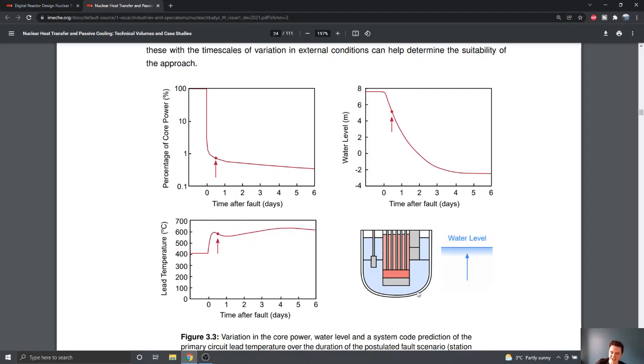You can imagine this is sitting in a really cool bath below where the water is, but above, these regions of the reactor are going to get really hot. And so you might naturally be concerned that these components near the top, or maybe the shell, the reactor vessel itself, might start overheating at the top first. So this is the condition we're going to look at with the CFD model. We're looking at a very small snapshot in time, and we may be able to do a steady state analysis or a small local transient to look at a specific condition. And we have to do that, of course, because we can't run a full 6-day CFD model with this.